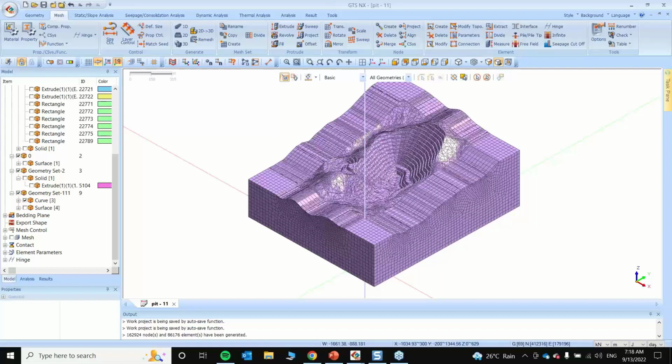So at the value where the model reaches divergence, that is when the software will calculate the shear strength at that particular moment just before failure against the original parameters that we had set for the material. That ratio becomes the factor of safety for that particular model.